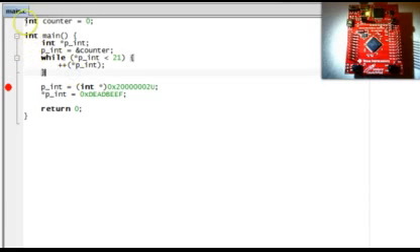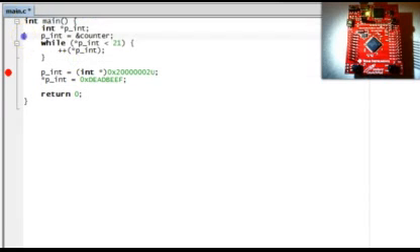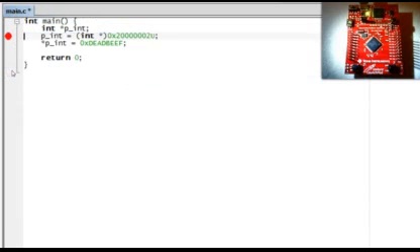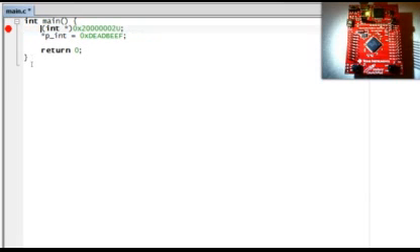Clean the code up to leave only the pointer stuff. Actually, you won't even need a separate pointer variable because you can dereference the pointer cast, as you will see in a minute. In lesson 3, you used pointers to int, but ARM registers are unsigned, so change the pointer type to unsigned int. Replace the fabricated address from lesson 3 with the address of the clock gating system register that you used to turn the GPIO-F block on.